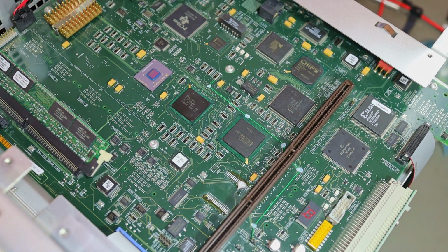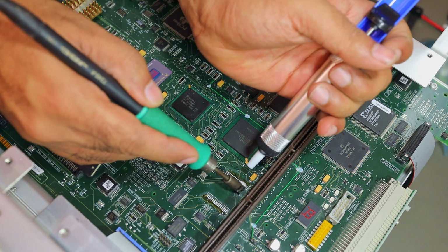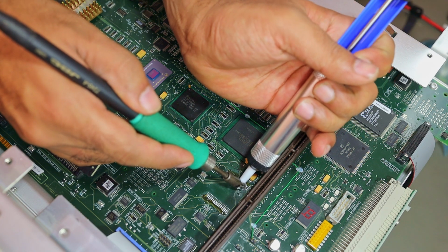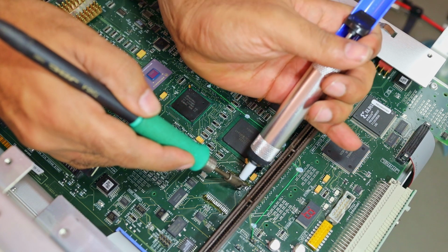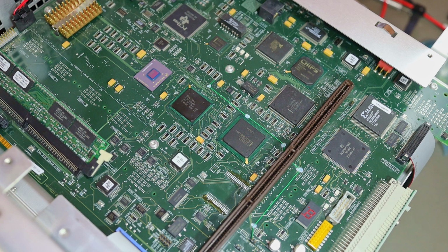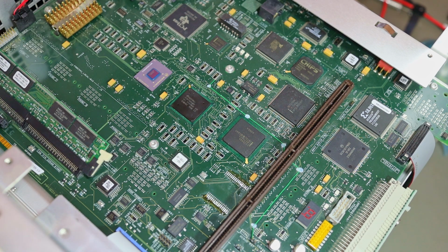Let's clean it a bit. Maybe I'll keep using this big soldering tip and use the solder pump to get this big blob off. Otherwise I'll use a ton of desoldering wick, and they are quite expensive. Now most of it is gone. A little bit remaining, and now I'll use my wick.